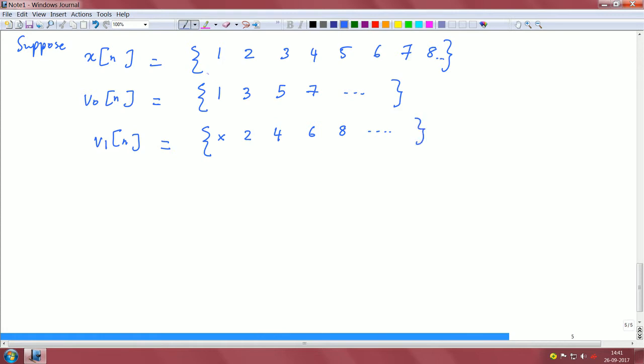So basically if you introduce a delay, the reference something here which would have been some element in the past before time 0, let us say that variable is x, right. You will have x, if you delay that you have x, 1, 2, 3, and so on. Now if you downsample you get x, 2, 4, 6, 8, clear. So this is a dummy variable indicating some value that would have been possibly before time equals 0. So this is basically time equals 0.